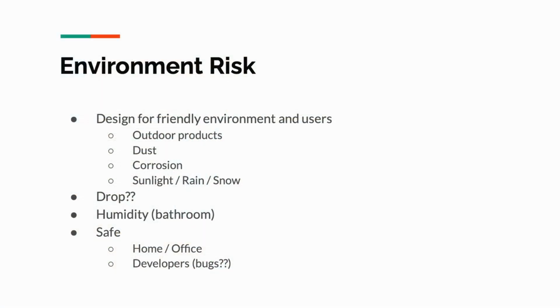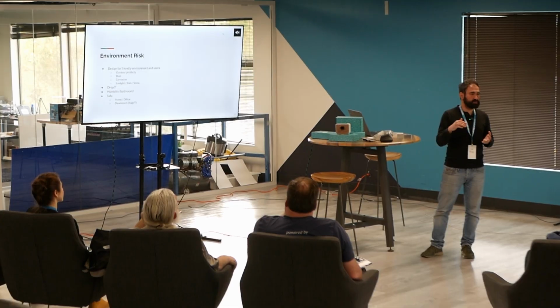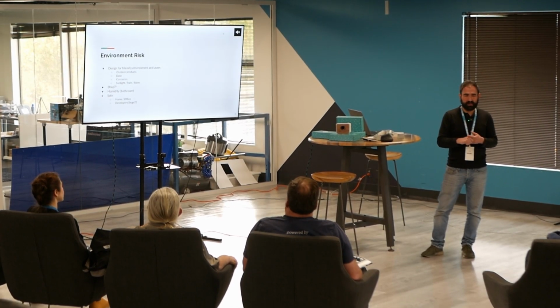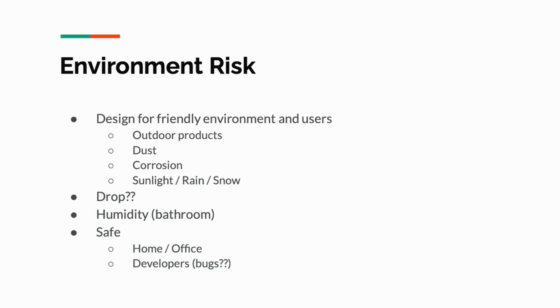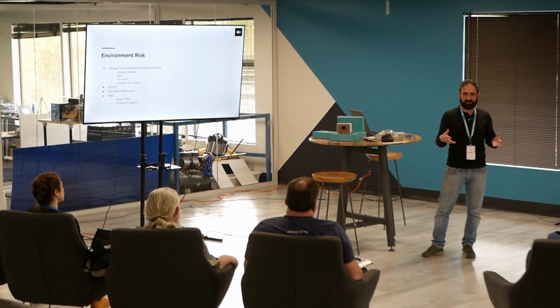You're dealing with corrosion and humidity when you're outdoors, so you have to go with IP ratings. IP68 is probably a very high bar for being dustproof and weatherproof and all that. But to get IP rated, you have to go to an environmental testing lab, where they will put salt on your product and see if it's going to corrode in the outdoor environment. They're going to spray water jets from different angles at the product to see if the water is going to get in. And there's sand, and different grains of sand.